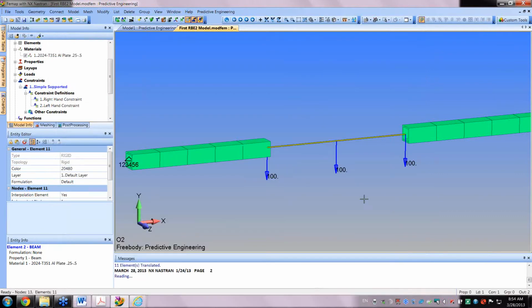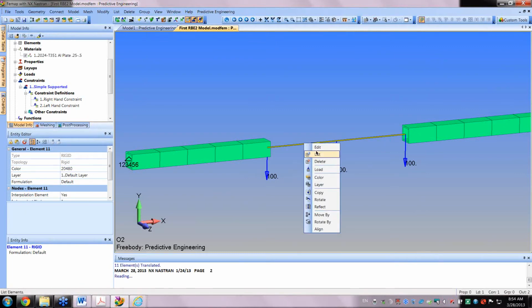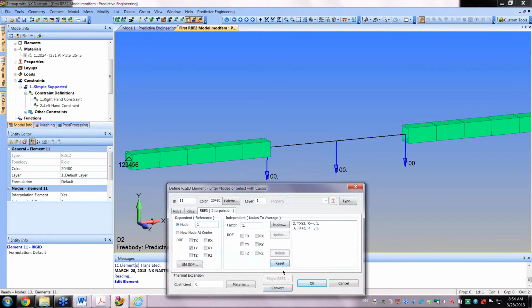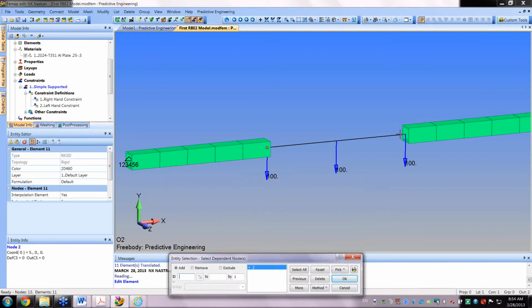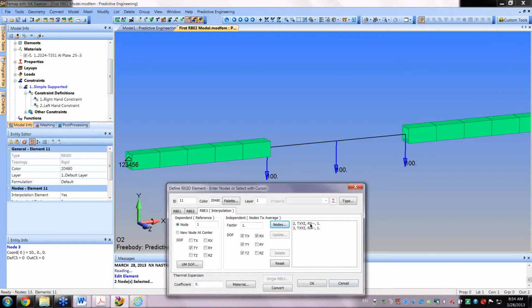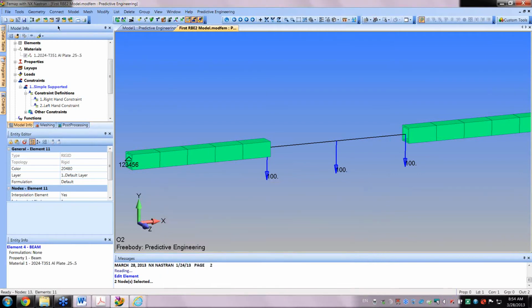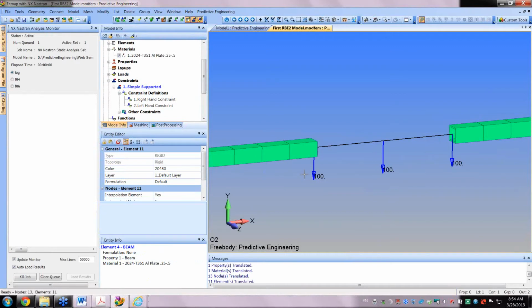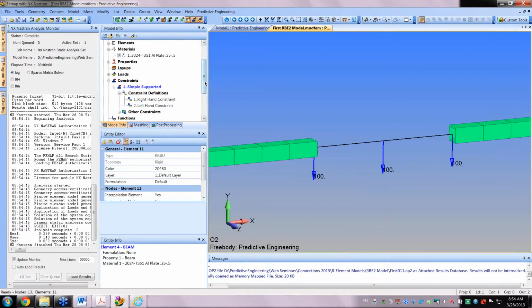Well, fine. You'd think, if it was like a standard linear analysis, it would tell you what degree of freedom was unstable. Well, some of you guys out there already know what the problem is. The problem is that this makes sense, but it's like a beam element. You got to prevent drilling. You can't drill down the length of the element. So you got to keep it from drilling. So we got to grab the Rx degree of freedom. There. Of course it runs.